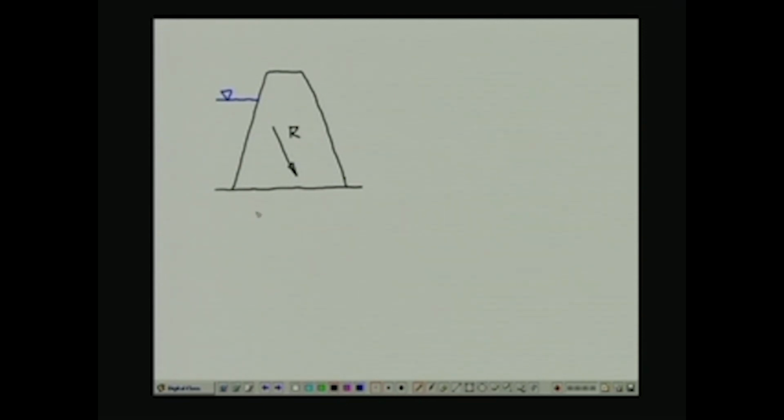Now we could have, for instance, bedding orientation of this type, and this is going to be the most favorable orientation because, as we know from our previous discussions as part of this course, the available shear strength of rock is going to be more if it is subjected to deformation perpendicular to the bedding planes than in the direction parallel to the beddings.